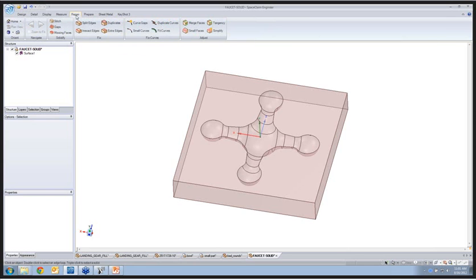So I took a look at the model. And of course, when I see a surface body, I immediately go over to the automated tools and try to stitch things together. I generally run in this order. I showed you stitch and gaps and missing faces. I don't think I touched on gaps, but it's just a sliver opening, and the idea is the same as missing faces. SpaceClaim finds them and heals them up automatically.